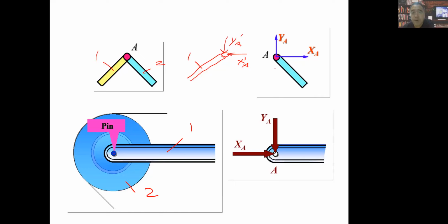So if you know its value may be like 10 kilonewtons, then you will immediately know XA prime will also equal 10 kilonewtons. You know why? Because a pair of action and reaction forces will always have the same magnitude, opposite direction, and be collinear, coexist, acting on different bodies. You know, that's a useful trick, I think.